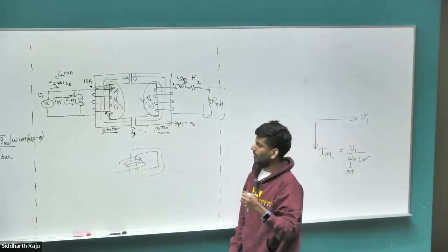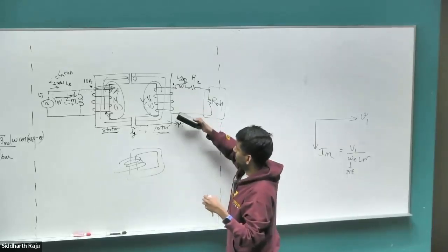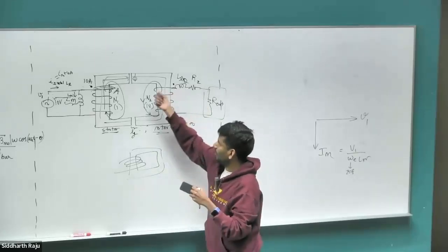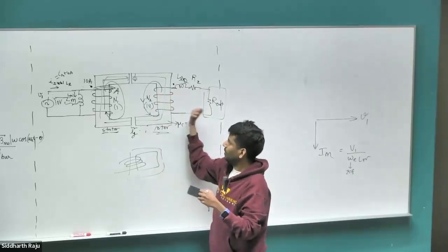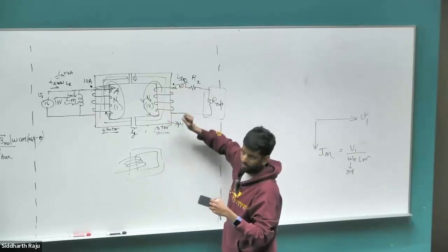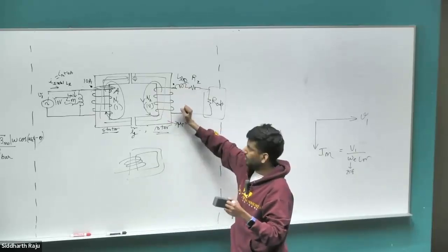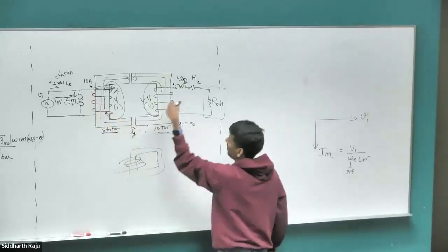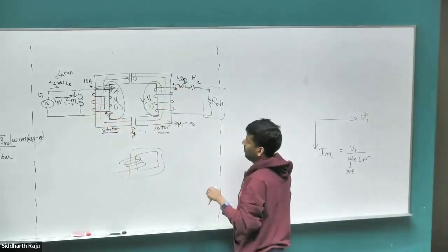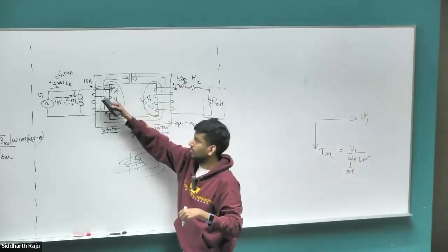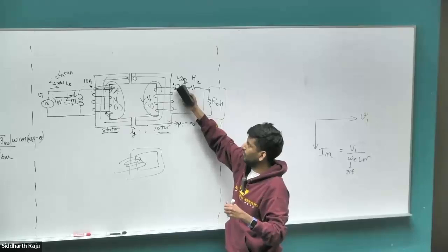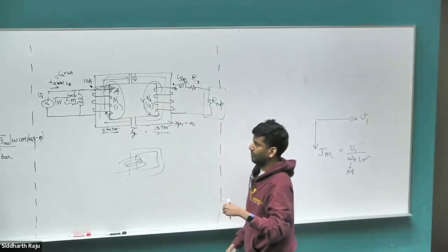That's the terminology. You can move the dot from the top to the bottom just by rewinding the coil: instead of coming out and going like this, if I flip the winding and reverse it around, the dot moves to the bottom side. There's no complexity to it. If the voltage is positive here and negative here, the voltage will be positive here and negative here, if the dot is on the top for both cases. If the dot was flipped around, the positive would be here and the negative here. There's nothing particular about the transformer having positive voltage on the top or the bottom.